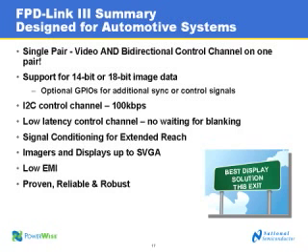You won't have necessarily multiple cameras sending video data to a single serializer and deserializer. Now, if I can just take the question a bit further, I think maybe you're asking about having multiple I2C devices sitting off of that serializer on the remote side. And absolutely, all of those can be addressed.